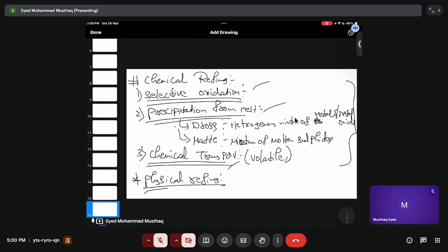And deoxidation you use in two ways, whether by poling or gaseous reduction. Poling is nothing but you add wood. Wood is mostly made up of carbon, and carbon will reduce whatever the impurities are present in it. And gaseous, again the same, methane, ethane or higher hydrocarbons to remove our impurities. Okay, that is about fire refining.